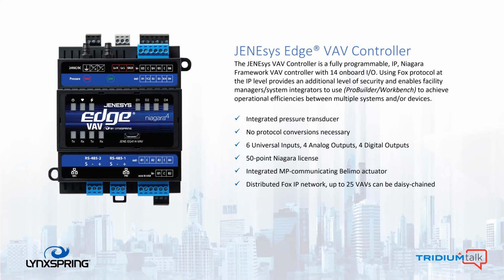All right. Now we're moving into an Edge control or Edge VAV controller. The Edge VAV controller is pretty unique. It is using the same hardware framework as the 414 and the 514, except we've integrated a pressure transducer. Pressure transducer in many ways is leveraged for our VAV application. However, if you wish to use this device in a different application that requires a pressure transducer, you could do so.